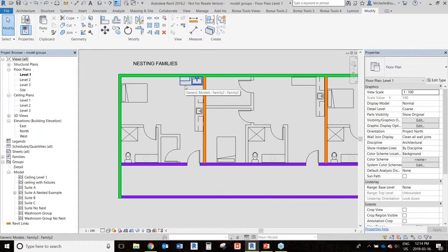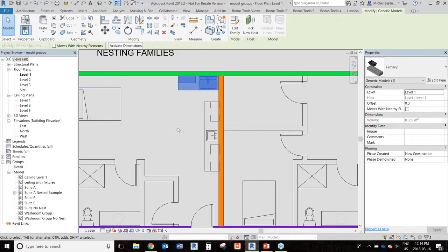So it's your call to make the best decision on when this might start to become more final, because that's usually also the time when your model has a lot more in it. You have a lot more details done. The file size is starting to get a bit bigger. That's a lot of the times when you can start to see some processing warnings. So if you can take that out of the group, that might save you some time. It also might give you some more consistency with not having to fix your groups.